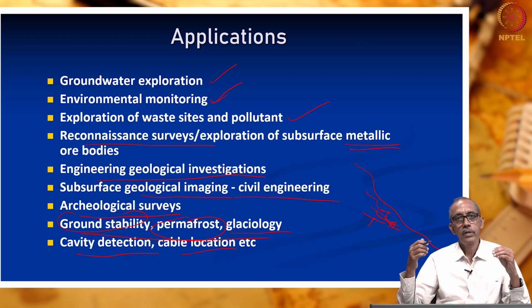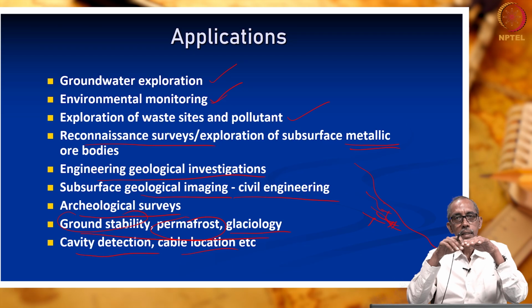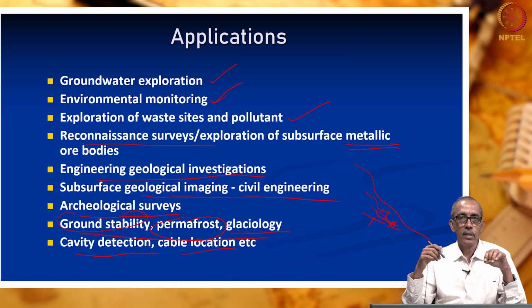In electrical resistivity tomogram, we conduct survey both in profiling as well as in sounding, which means we carry out sounding at many locations within our study site. So, we understand the variation in resistivity in different locations vertically below the surface of the earth.